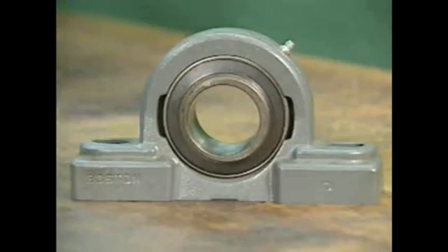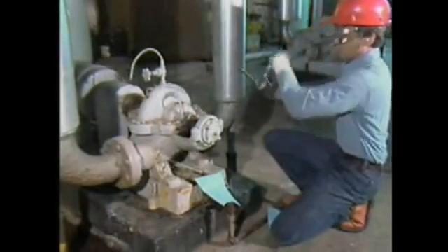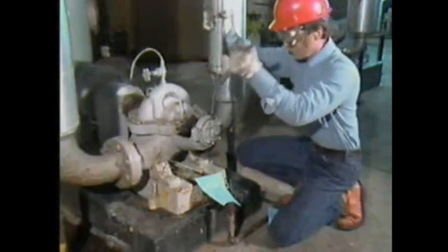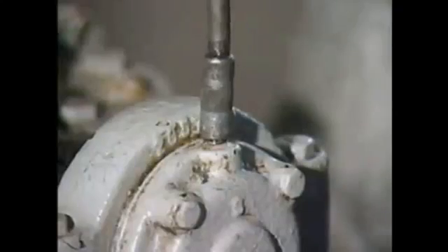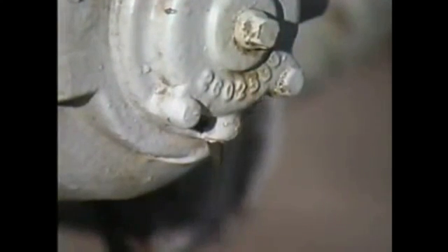Many bearings that have to be greased are contained in housings that have grease fittings. A grease fitting is a small rounded projection on the housing that has a hole in it. To grease the bearing, a grease gun with a matching fitting is attached to the fitting on the housing. When this method is used, it is often necessary to remove the housing drain plug to allow old grease or excess grease to drain out as new grease is pumped in.